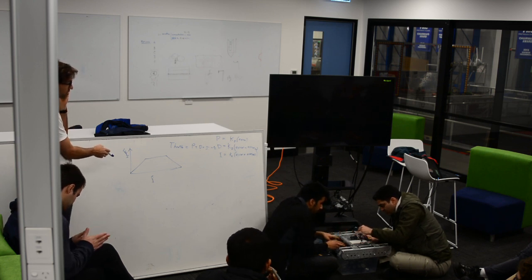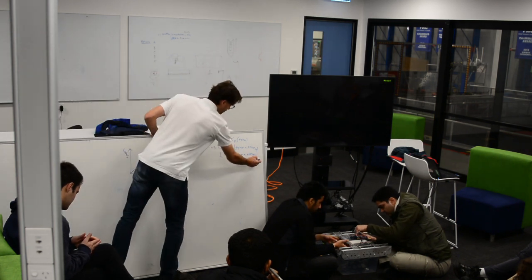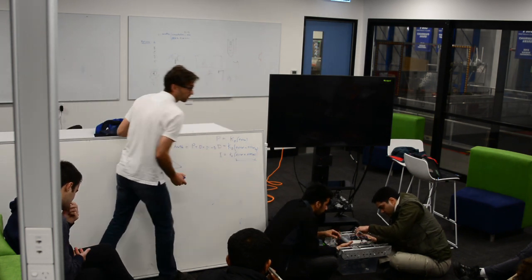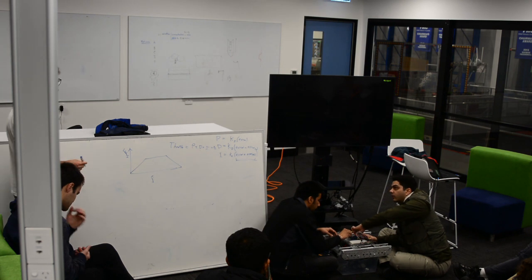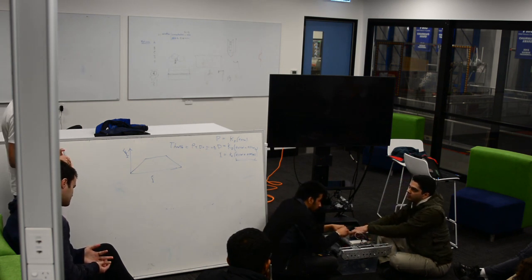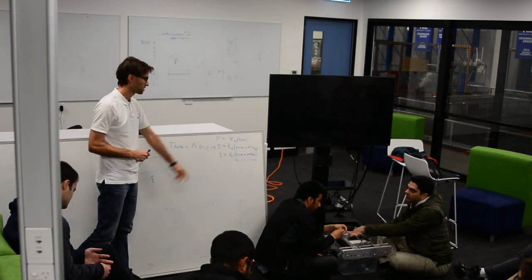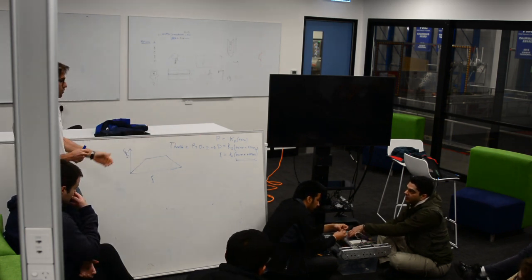Now, you could also think, if you can figure out a way to measure speed, so we're measuring position. How would you measure speed if you wanted to? Well, you've got to look at the timing between these pulses, or the timing between a range of pulses.